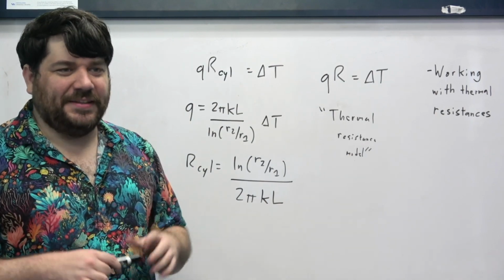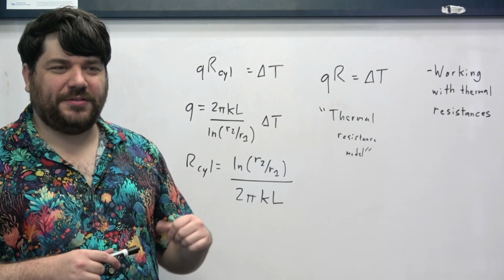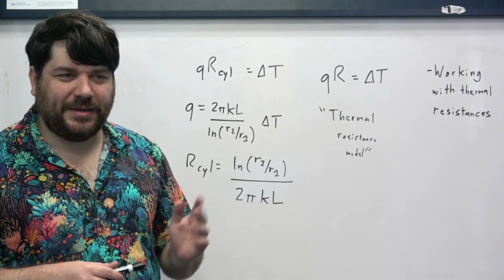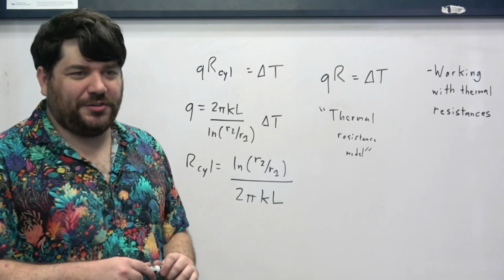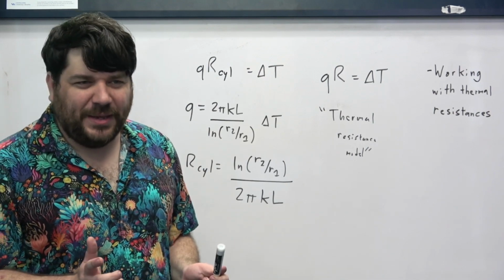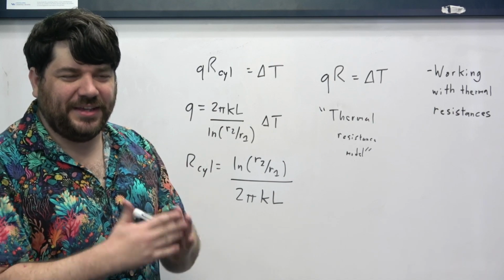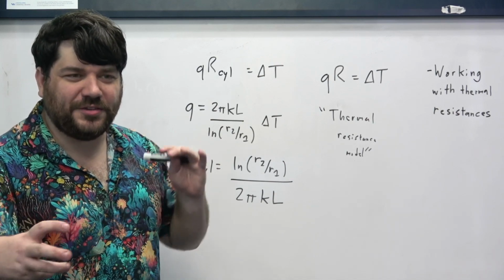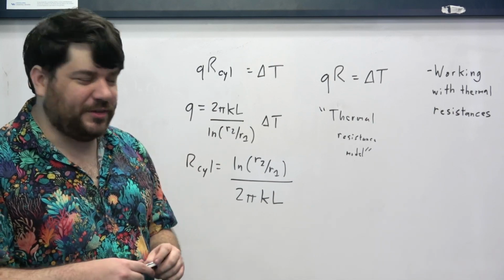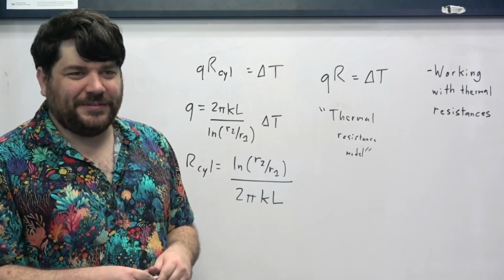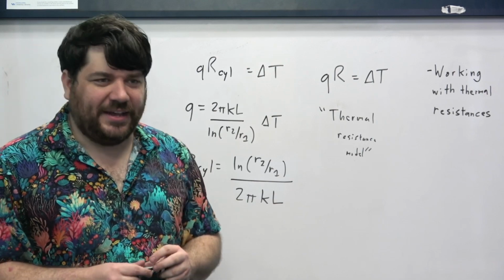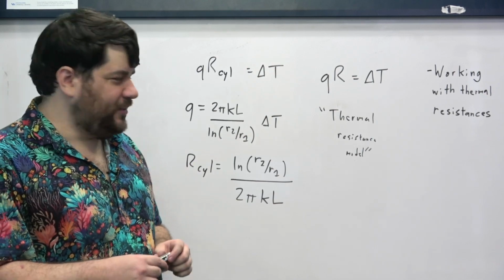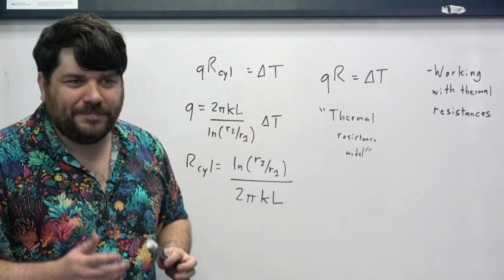So in the cylindrical case, if we want to maximize heat transfer through the system, we minimize the thermal resistance, so make the L larger. Why does making the L larger help? Because by making the L larger, you're making the surface area over which the heat transfer takes place larger. So in the same way that it happens in the planar system, you would expect to get larger heat transfer rates for the same temperature difference.